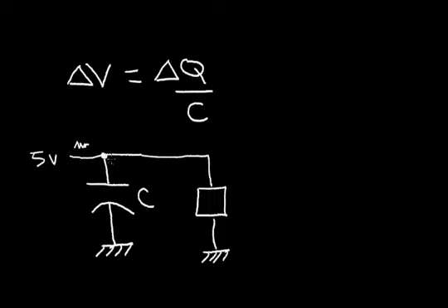And it would discharge rather quickly, but for a very short time it could help to hold the charge there. And notice that I drew the bottom plate of the capacitor with a curve. That's sometimes done with a capacitor that has a polarity, where this is the plus terminal of the capacitor and this is the minus terminal. And for very large capacitors, very often they'll have a polarity. It'll be an electrolytic capacitor.